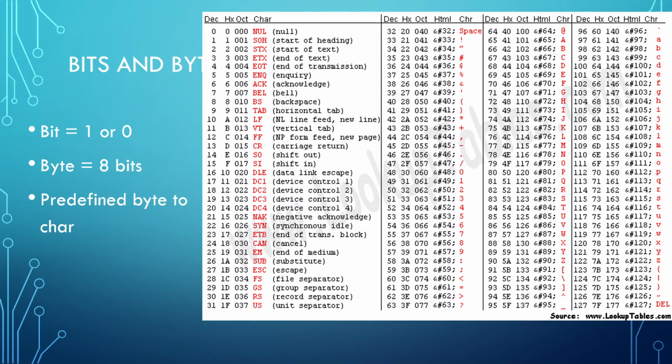You guys ever have to start dealing with serial? I'm going to hit enter, and it doesn't send the actual enter command, but I want to send it enter. But you have to tell it either a new line or carriage return, or those two things. And depending on what hardware you're talking to, it's going to matter whether you send new line or carriage return. So it starts to get really annoying at that point when you are dealing with this type of thing. So just something to be aware of.